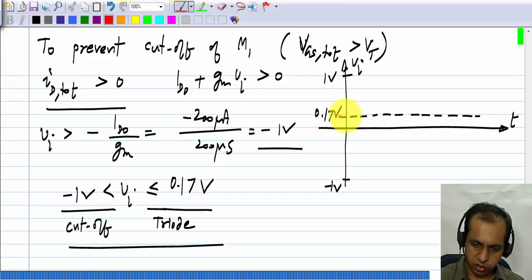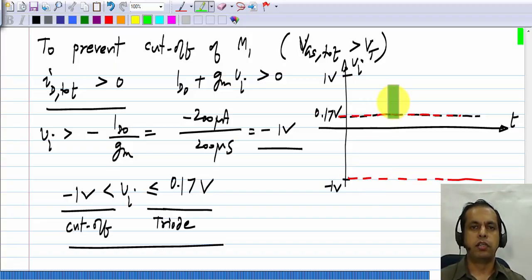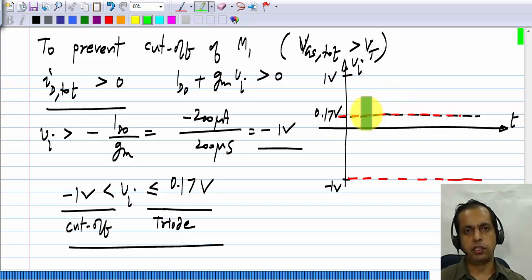So these are the limits, and as far as we are concerned, according to our crude approximation, within these limits it behaves like a linear amplifier. We know that as the input amplitude increases, the distortion, the nonlinear product slowly increases because the small signal or incremental analysis with linear approximation breaks down.